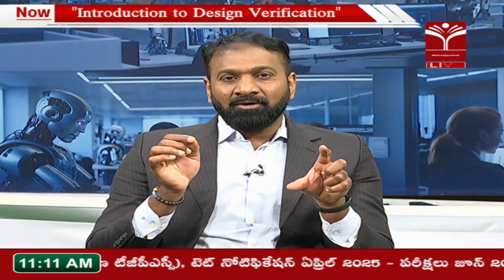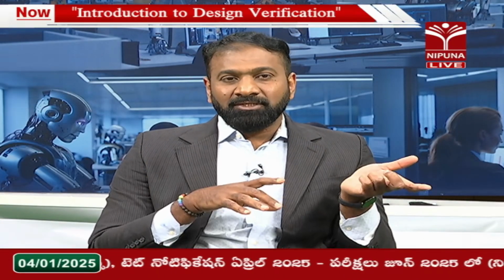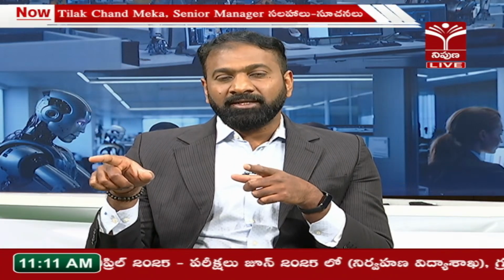Yes. Right. So whenever there is a design progression, you always go back to see if the new code is added or not. You cannot rely on the same test bench. You have to ensure the new tests are added which check the new constructs of the design. If that does not happen, there is a mismatch. So you are not fully verifying that new code which gets added, and that is where coverage comes into the picture. When you have new code, there is code coverage.